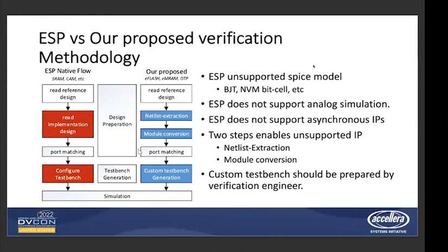However, to enable the extracted netlist for Verilog simulation, we have to modify the extracted netlist. Also, for simulation run, we need a custom test bench for our proposed methodology because ESP does not support the extracted netlist natively. Luckily, using Verilog language, we can create a custom test bench for ESP simulation.